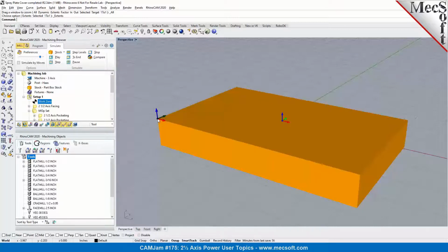And that corresponds to this work zero that you define here in our system. In that case, you're aligning your coordinate axes, or the coordinate axis origin, so everything will come out correctly when you machine. The second thing that Uday was explaining is that in some cases you don't need to do that. You set up your work offset and have a G54 come out, and wherever that zero is defined on your machine tool, that's where it's going to start machining. So I hope that makes sense.